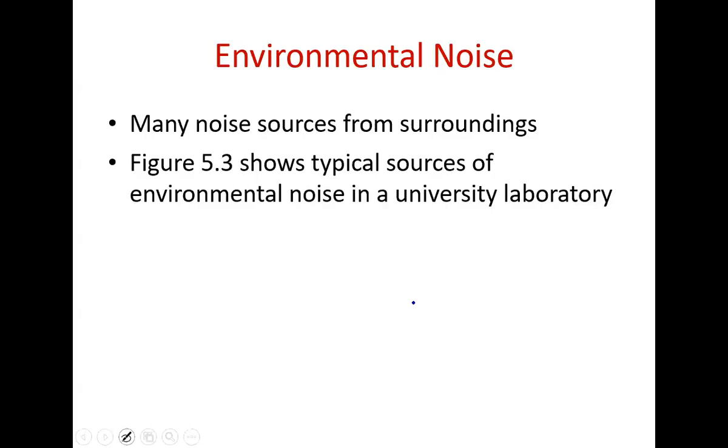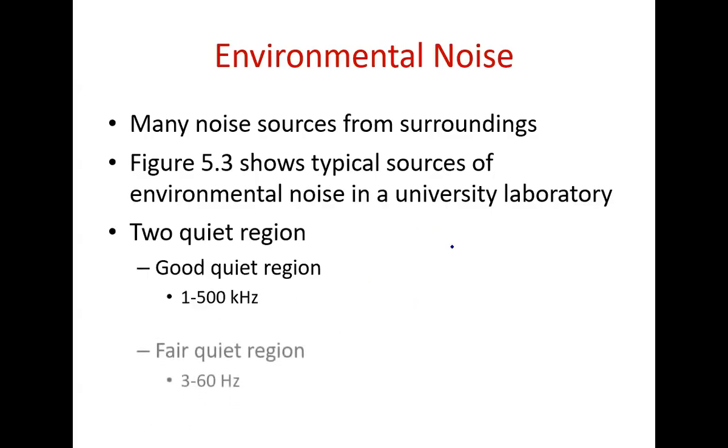Think about it: if you have a lab in the morning and students are coming in, or during the transition from one class period to the next, your instrument would pick up these environmental noises. I'll talk about those two quiet regions: a good quiet region, 1 to 500 kilohertz, and a fair quiet region.